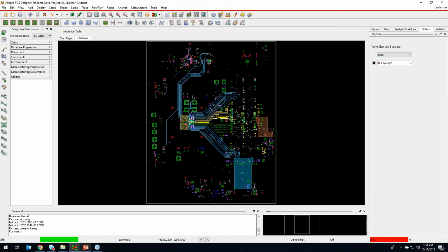That was about 100 signals on this particular relatively complex board. I think this has roughly 10 or 12 layers. So yeah, it was able to do that analysis in about 7 to 8 to 10 seconds. So it's very fast. It's not anywhere near what you typically see signal integrity simulations take.